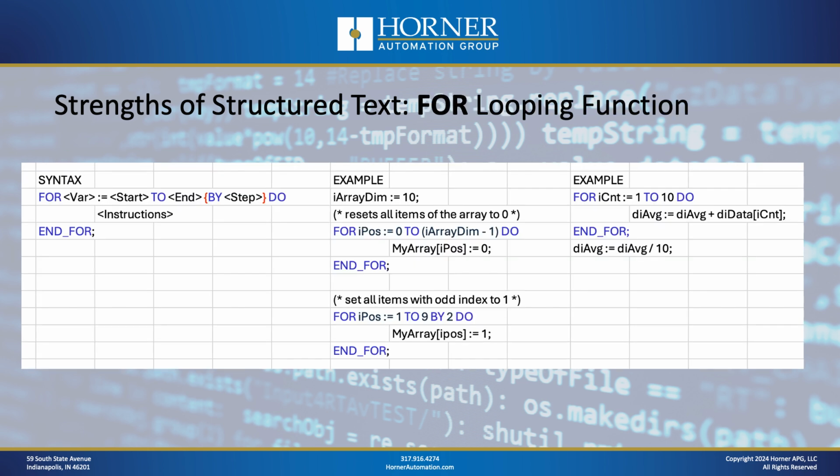All right, let's talk about some of the looping functions, starting with for. There's basically three looping functions, and this is the first one, for, and this is the one I probably use the most because the one danger of any looping function is you forget that it doesn't get out of the loop. In a short matter of time, in a quarter second, you're going to trip your watchdog timer and have a fatal fault. The system shuts down.